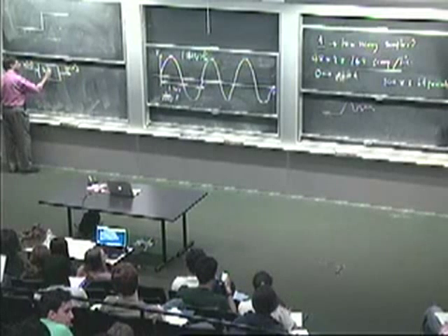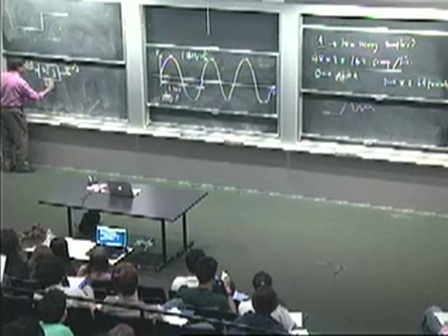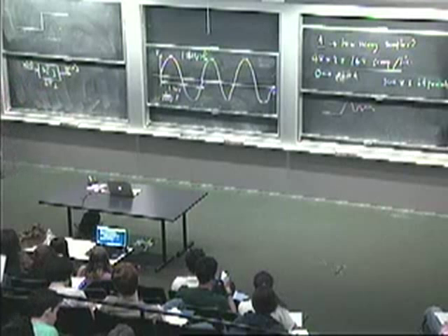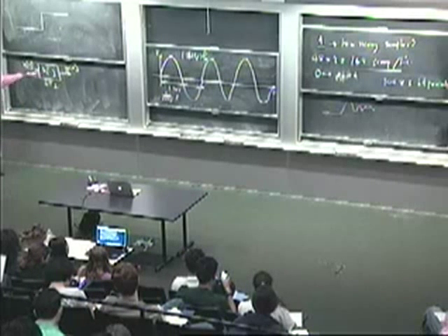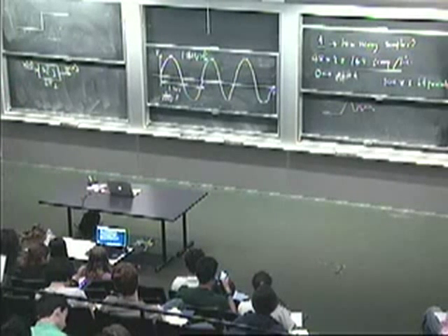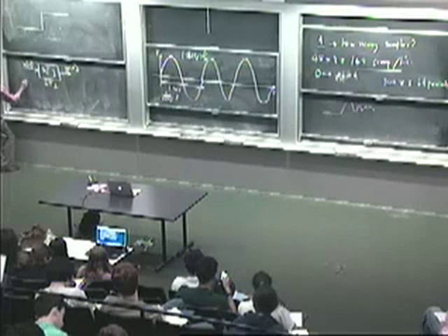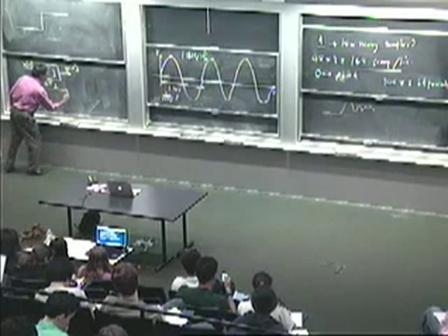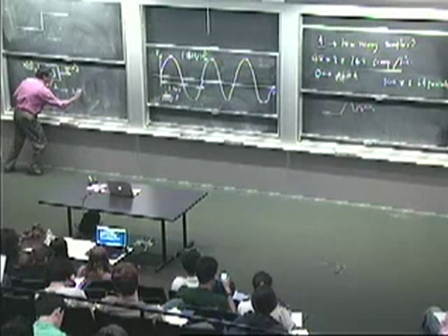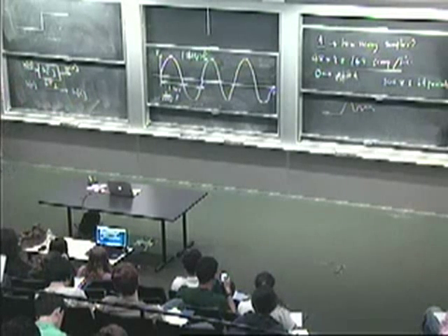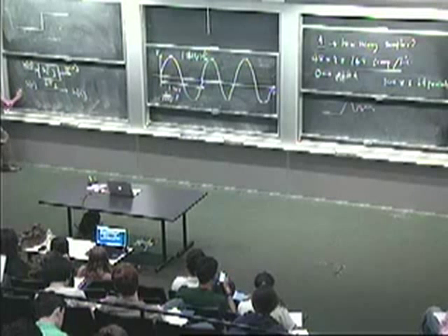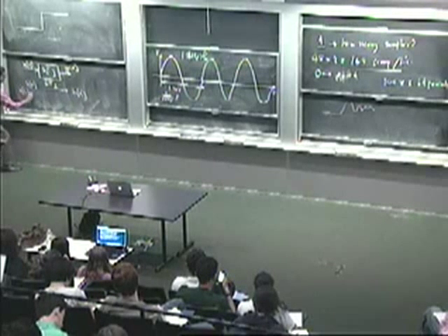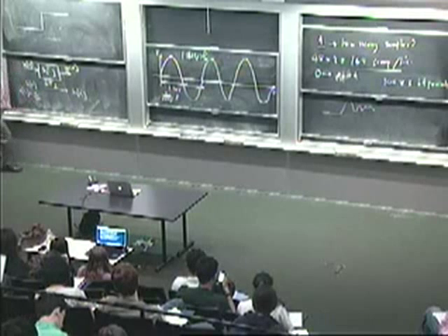So we're talking about an LTI channel, linear and time invariant. We talked about characterizing it by its unit sample response. Unit sample response means put in a unit sample function, you get out an output that you're going to call the unit sample response. Put in an input x[n] that is a summation of such things.